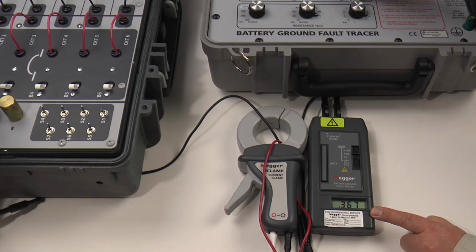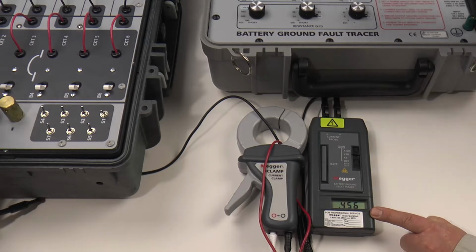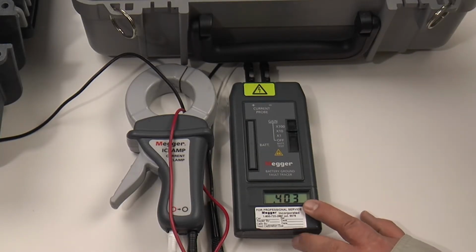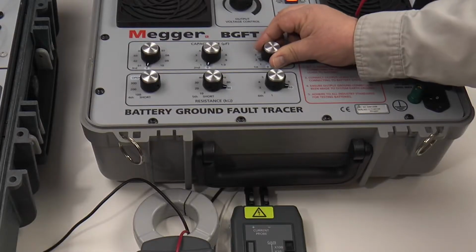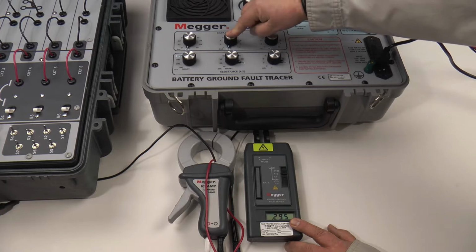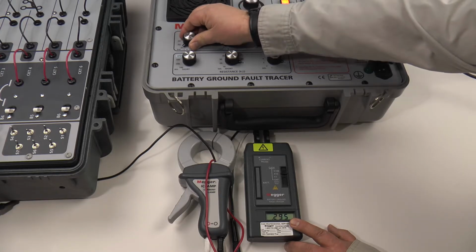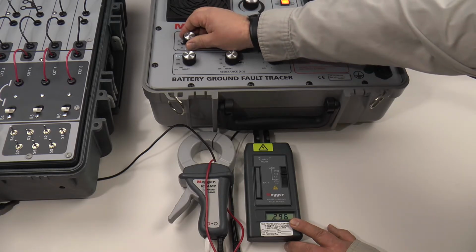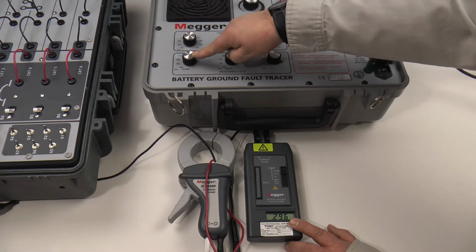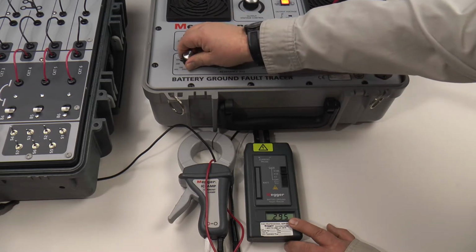In this case, you can be sure the fault is purely resistive, and we can proceed with just tracing the fault. If the reading on the receiver is going down, continue increasing the capacitance, moving from knob 1 through 3, until the minimum value on the receiver is achieved. At some point, the value may start to increase. We want to adjust the Wheatstone bridge to achieve the minimum reading on the receiver.